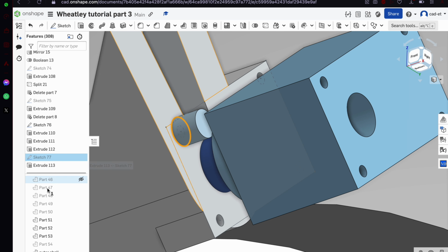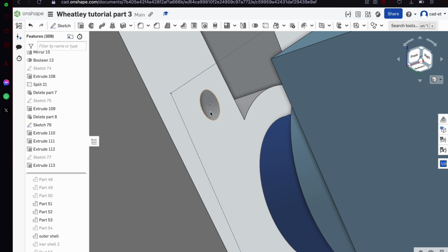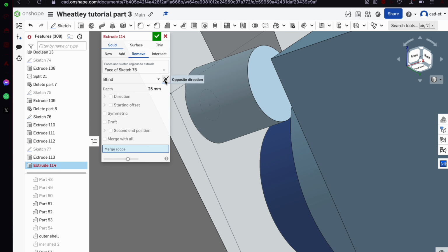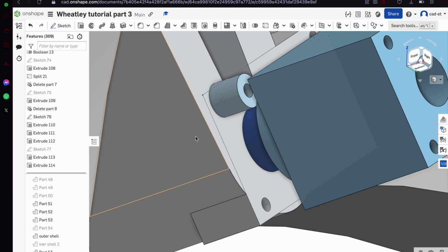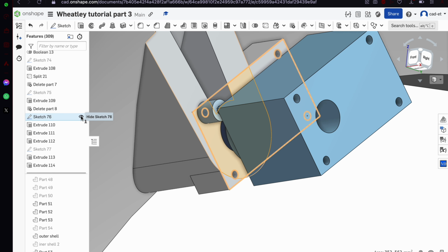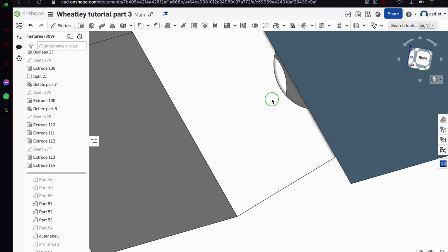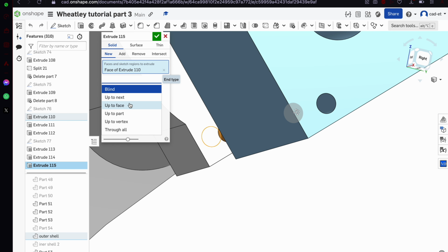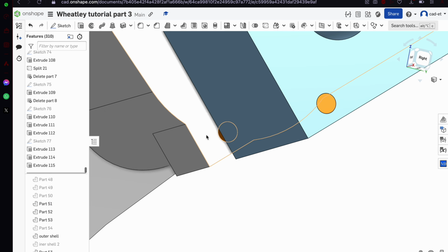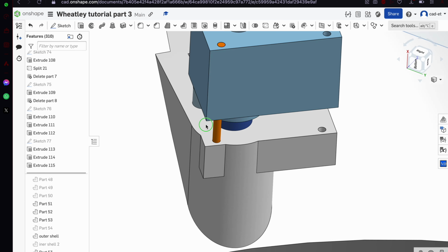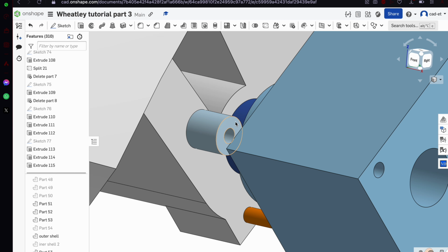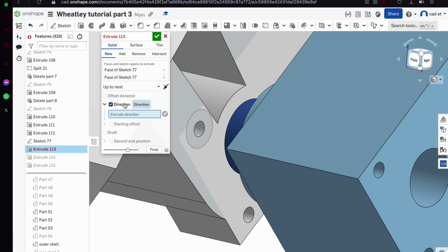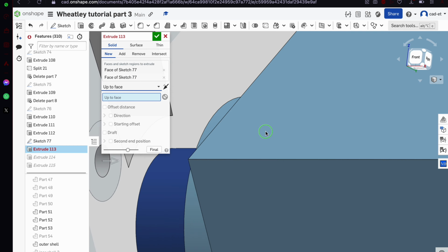Luckily, I've got a plan for fitting the bearing in, which will involve splitting the design of it into two parts. The two parts will be a top and a bottom. The main bearing goes in, then the top bit can be slotted in, rotated round, the bottom bit can then go in and it will lock the bearing in place. But it also enables us to get the clearance to actually mount the bearings.